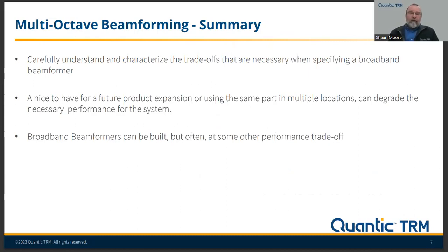Sure. So basically, when we talk about any kind of broadband network, whether it be a beamformer or any other device, you always have to understand the trade-offs that are incurred by trying to increase bandwidth. Bandwidth is never a free commodity. It always comes at a price. Sometimes it comes at insertion loss. Sometimes it comes at our ability to either amplitude or phase match. There are lots of reasons why you'd like to do it or need to do it. There are other times where it may not be quite so advantageous.